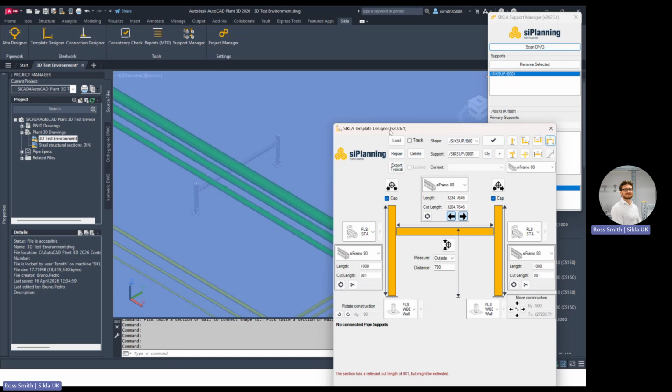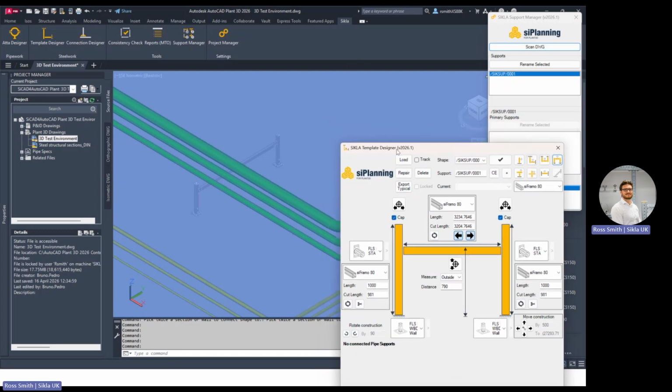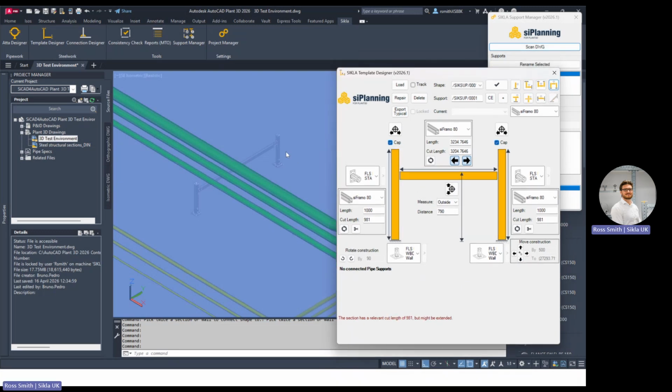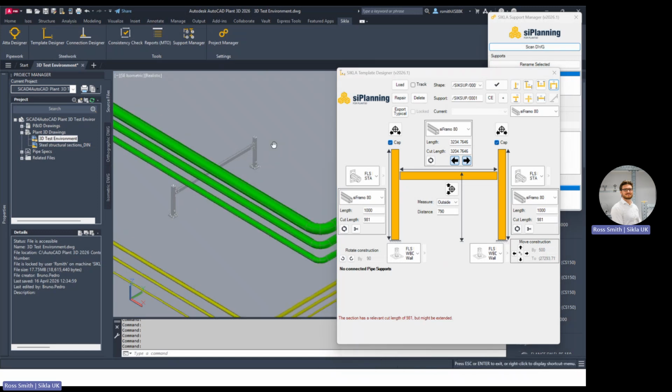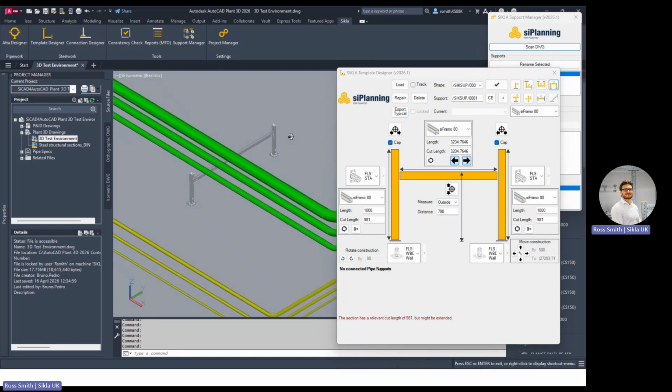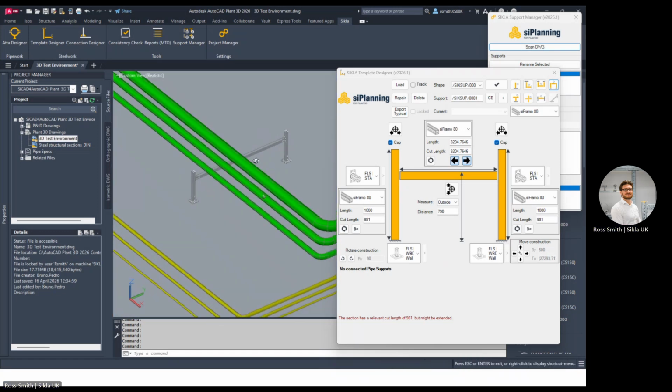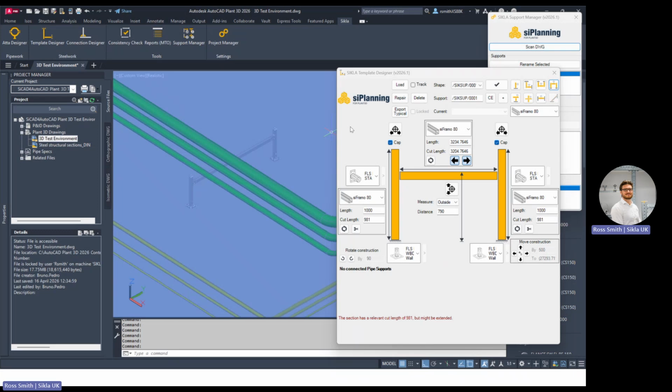Unfortunately, that is something we're dealing with at the moment, and it should be fixed soon. But going forward, everything else manipulation-wise you can use your middle mouse button to pan. You can control the middle mouse button to skew, and Shift and your middle mouse button to rotate. That's fine. That has no effect. Okay.